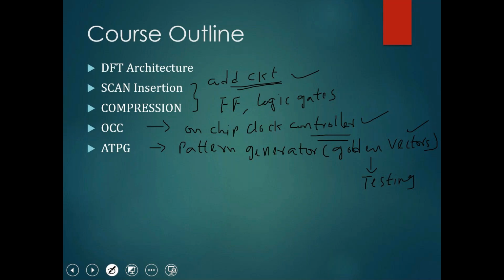If it is design, if you add it, we give it to the physical design team. If it is pattern generator, we generate the vectors or patterns or test cases and we give it to the testing team. So before giving to the testing team, we validate them. We can also validate the patterns we have written. So that is called simulations. You simulate, which means you apply a value on the software in which the golden vectors have been written, and you observe the output and see whether it is proper or not.